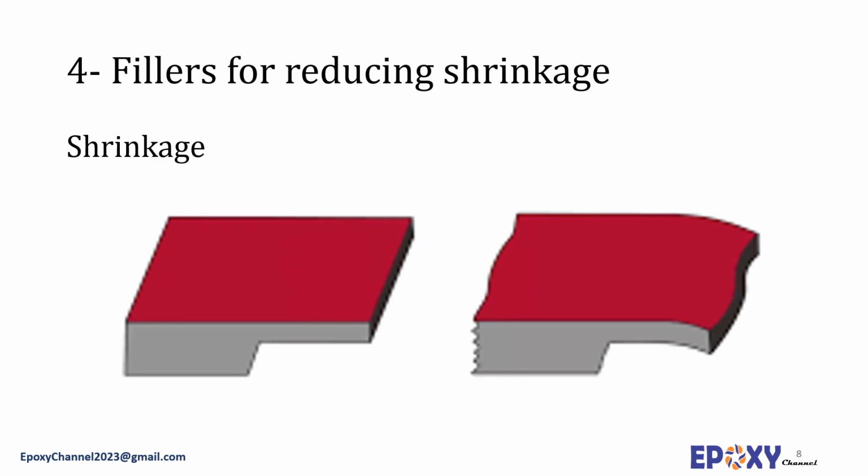Nearly all polymeric materials shrink during solidification. Sometimes shrinkage happens because of escaping solvent. Even 100% reactive systems such as epoxies and urethanes experience some shrinkage because their solid polymerized mass occupies less volume than the liquid reactants. The result of such shrinkage is reduced dimensional stability or the occurrence of internal stresses at the adhesive substrate surface. Reduction in this shrinkage can be accomplished by introducing fillers which reduce the rate of shrinkage by bulk displacement of the resins in the adhesive formulation.